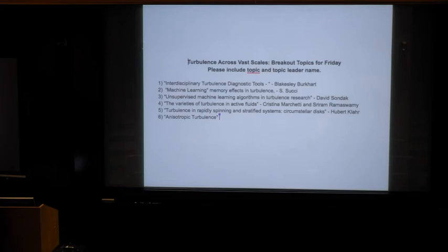Just one remark regarding your question. I don't remember exactly why, but in the simulation, when you talk Reynolds 10 to minus 4, I think it's a mistake to assimilate 10 to minus 4 to 0, because the two things are very different. At least in the numerical practice, it helps a lot to keep the nonlinear term alive, even if it is 10 to minus 4. Now, if you ask me why, I cannot now recover the argument, but I know there is one. So I wonder whether this could help in regularizing.